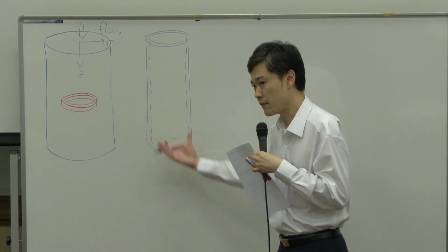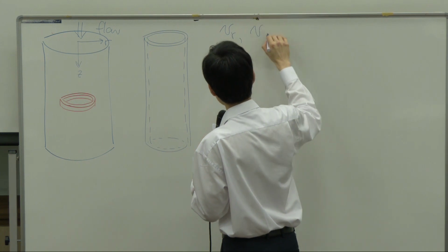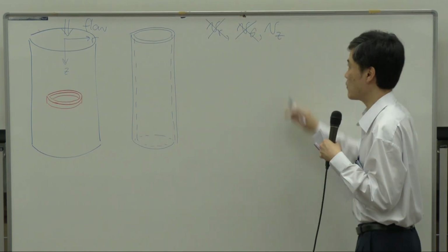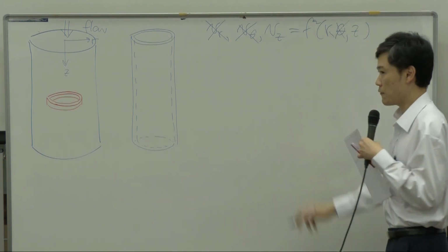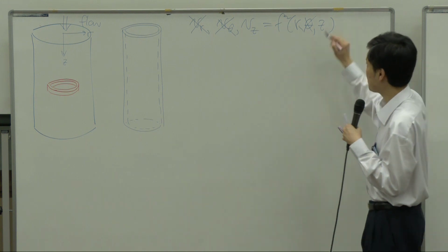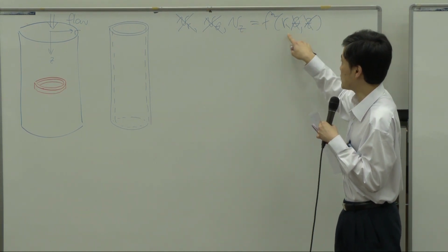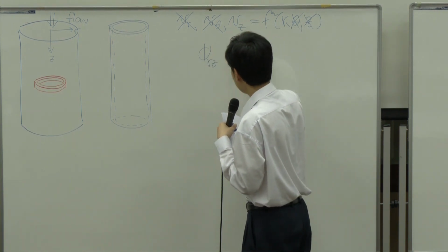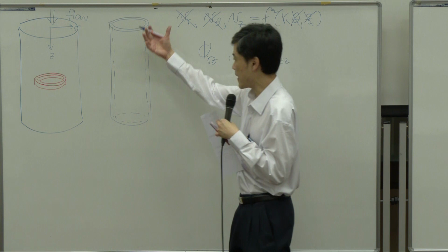So based on this shell of the momentum transport, you set up the flux. If you start again, we have VR, V zeta, Vz. There's no VR in this case, there's no V zeta in this case, only Vz. And Vz will be a function of R only. It's not a function of zeta because the system is symmetric. And if you assume that there's no acceleration within the pipe, Vz would no longer be a function of z. And having Vz as a function of R, we end up with fluxes of Rz, zeta z, zz, right?